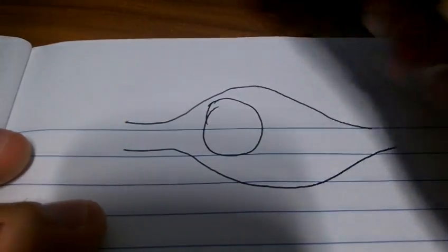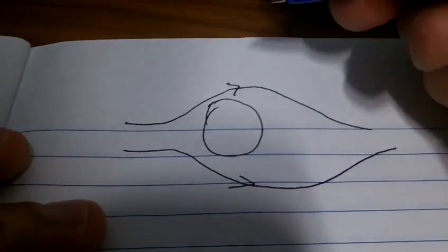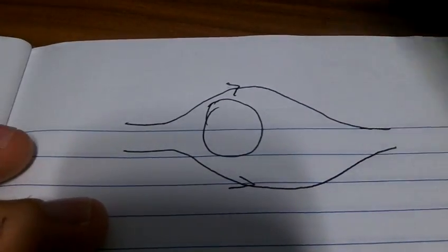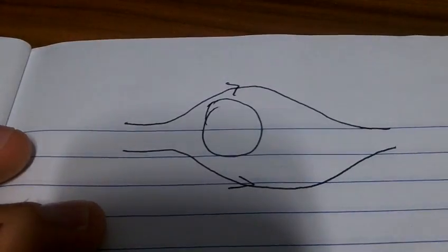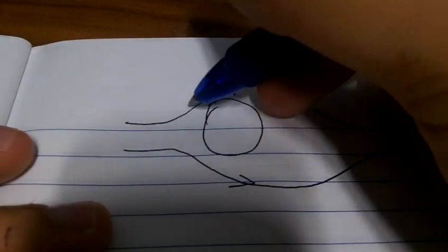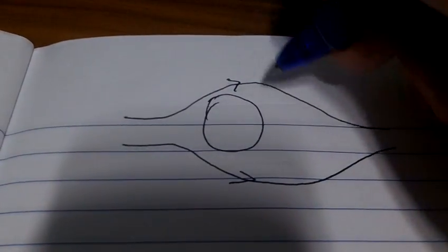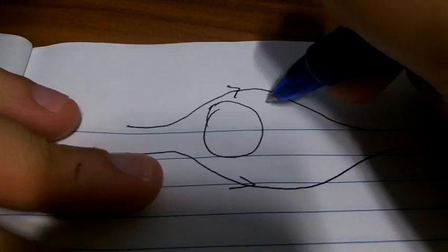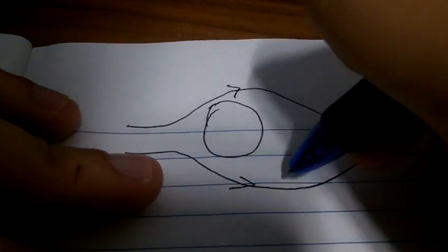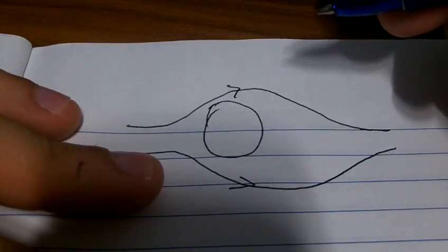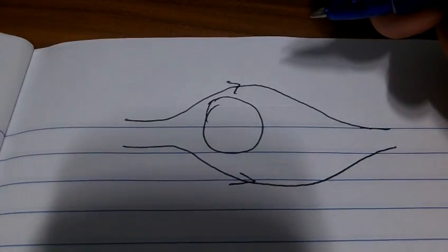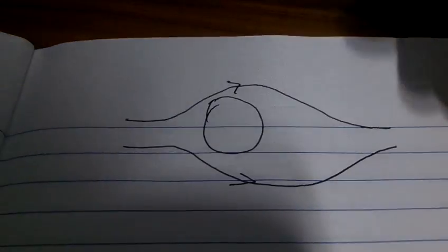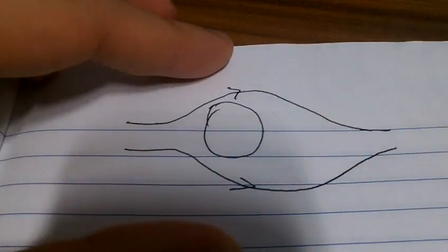Well, we know from experience that if we let objects travel through a fluid medium, such as a ball or sphere, and the fluid is flowing fast enough, you will have some turbulence here, because the fluid cannot converge back fast enough by virtue of its inertial forces. It has too much inertia to be pushed back here.